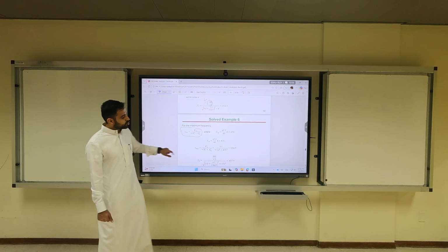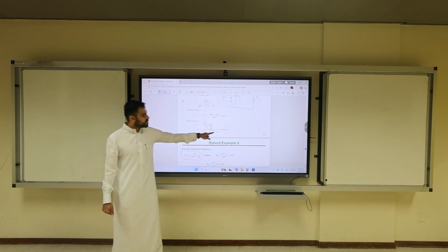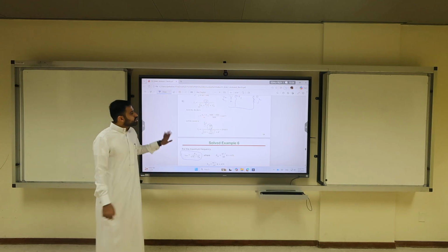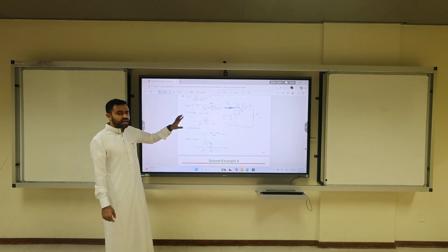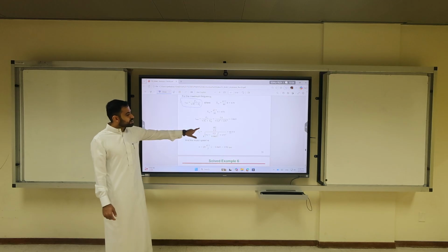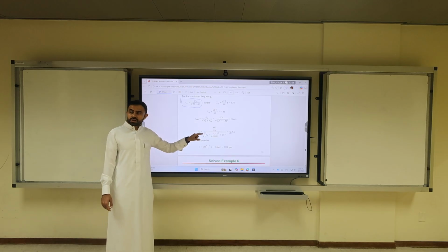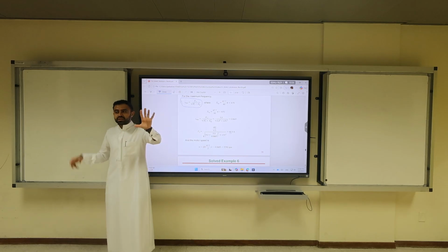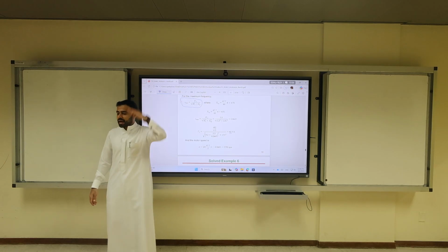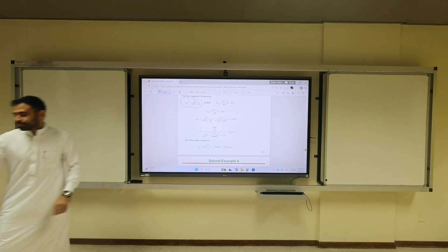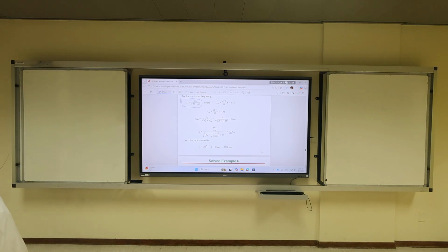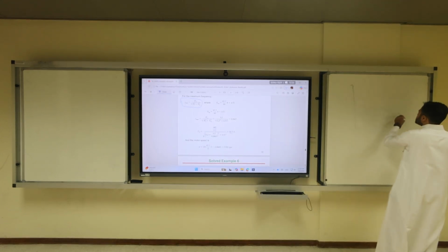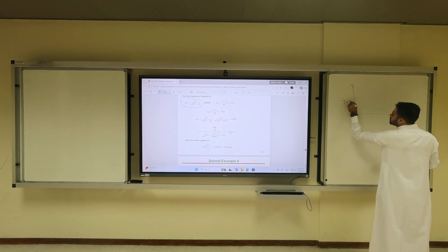And what do you notice here? 42.5 starting current versus 423.62. So this is not the starting current, this is the rated current. This is the maximum current. Remember, you're driving your motor to its torque, for frequency 60 Hz, you're operated at rated. Let me explain it from the curve's point of view. From the curve's point of view, where is your torque? 180, right?